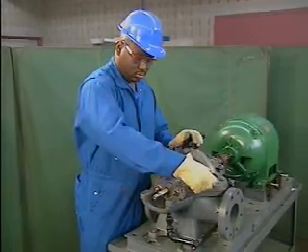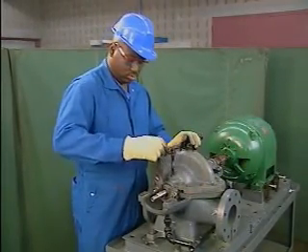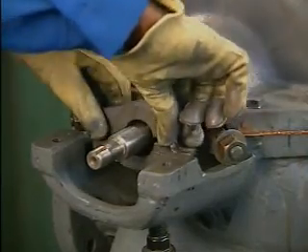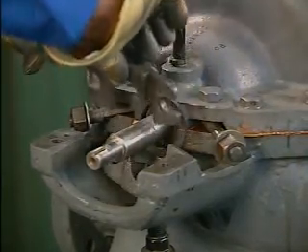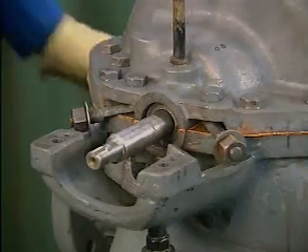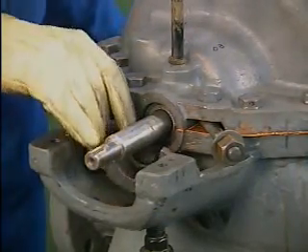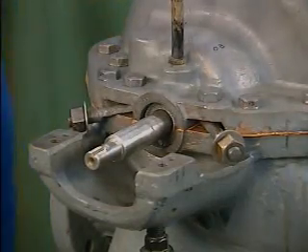The mechanic's first step is to remove the nuts that hold the gland follower in place. This pump has a two-piece gland follower that allows it to be removed from the shaft. If an application has a single-piece gland follower that cannot be completely removed, the gland follower should be tied out of the way along the shaft.